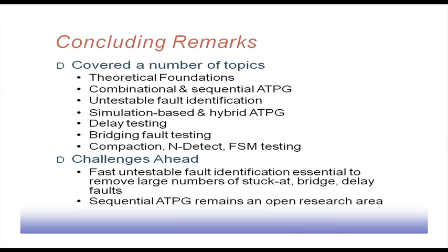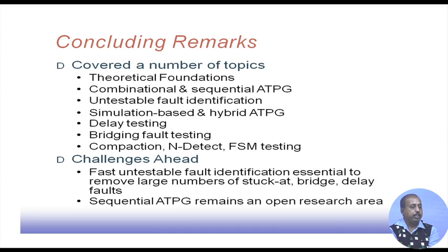What is required is that you just change the fault dropping criteria. So, to conclude, we have seen in test pattern generation some theoretical foundation in terms of the Boolean difference and all that. We have seen combinational ATPG, sequential ATPG. We said that under the scan conversion process, sequential ATPG is rarely used, excepting some partial scan based circuits, but mostly it is combinational ATPG that is coming into picture.